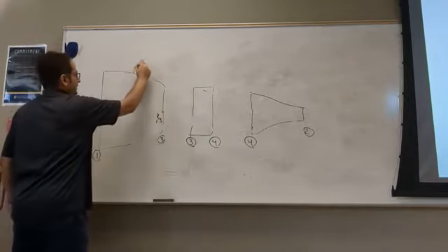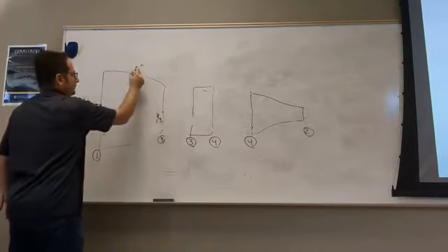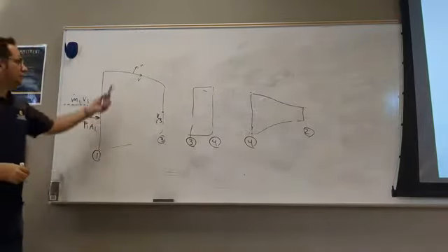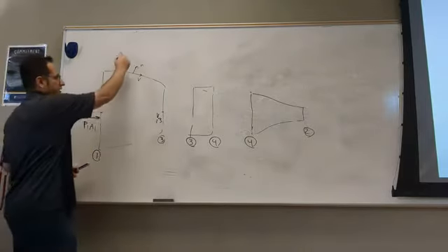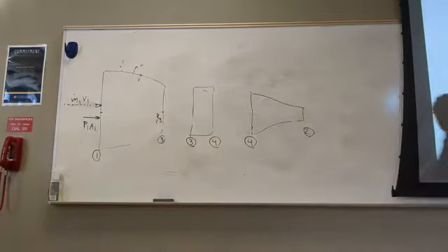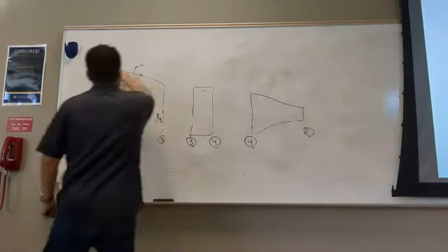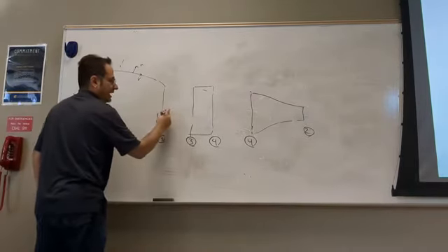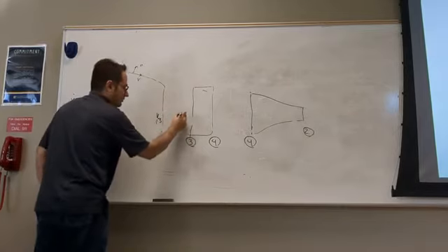So you go to the next step. What do I have here? You see the velocity is this way. V dot N over the top is what? Zero. You see that you have some pressure here, but it will cancel out with the bottom because it's perfectly symmetric. This is what I choose. This is not the geometry, not inside the tunnel, and not the tunnel. This is what I choose as my control volume, so you are free to make it perfectly symmetric. So there is no external load here. Then here, the velocity is this way, the normal is this way, so the actual direction of inertial force is this way, so you put opposite.